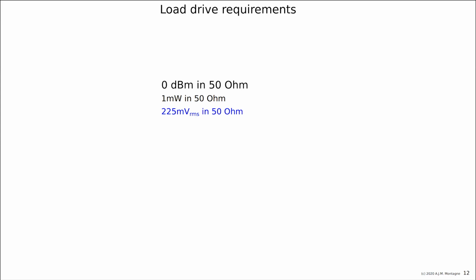But our amplifier is not going to drive root mean square values. It is driving peak values maybe. And now the question is, what is the peak value that it needs to drive in this 50 ohm? Assuming that it is a sine wave, then it is about square root of 2 times the RMS value. Or does the signal more look like a Gaussian distribution, like noise? Then, if you want to have less clipping than 3%, your peak value can be 3 times sigma, the standard deviation. So it is much higher than for a sinusoid. So this is a question that might become interesting.